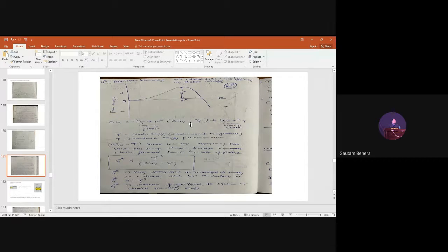But when we are discussing solid to liquid to solid transformation, we are not having this kind of strain energy, because we are considering the density of the solid and liquid to be the same. Volume change is the same, you can understand. Anyways, here I have already written delta G_B minus psi, meaning we are removing some volume free energy change because of strain generated due to formation of a particle.